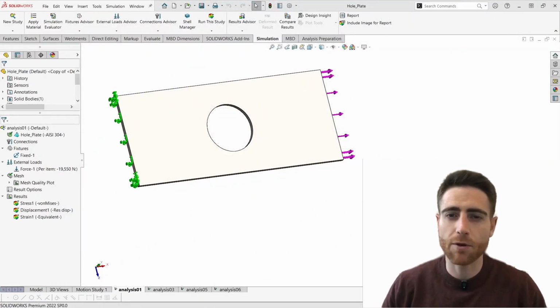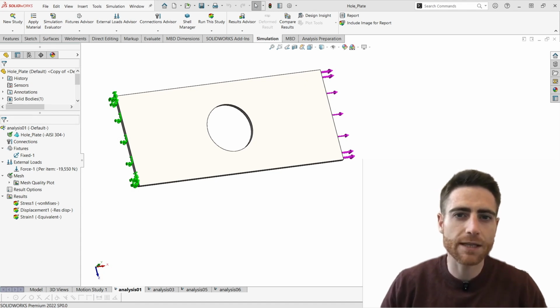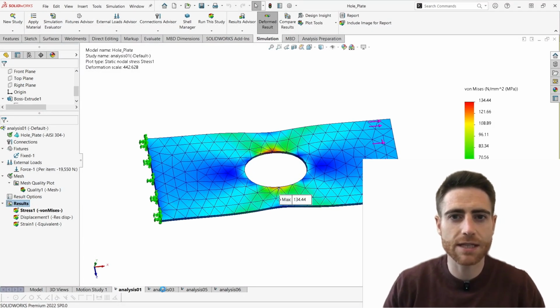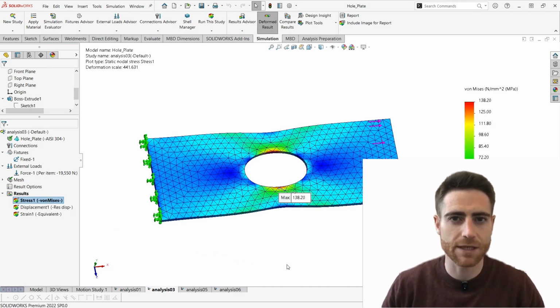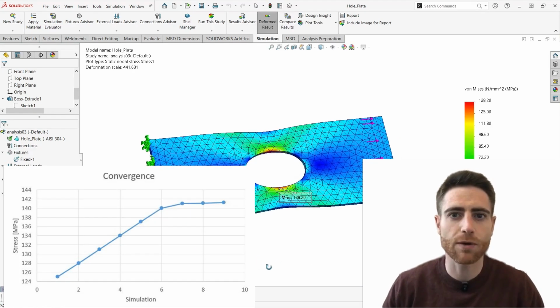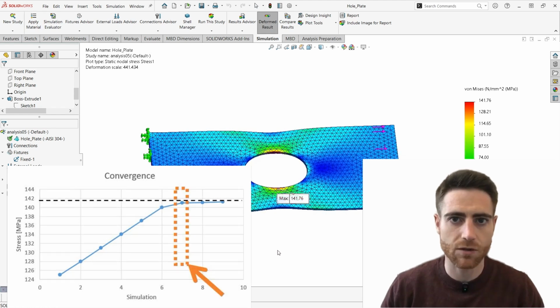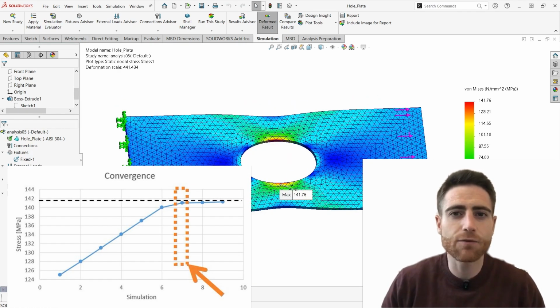Okay, before we move to our project, I wanted to mention one point. If you already did any FEA simulation training, no matter which software you use, I'm totally sure that you always review how to do a convergence analysis. The typical exercise is displayed with a hole in the middle where we fix it in one side and pull from the other side. The exercise consists of starting from a very poor quality mesh and moving on, increasing the size of the mesh until achieving the convergence. We do this basically because when we do any FEA simulation analysis, we need to have the confidence to trust in our results. Therefore, the convergence analysis is fundamental.